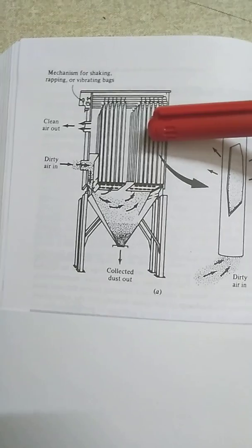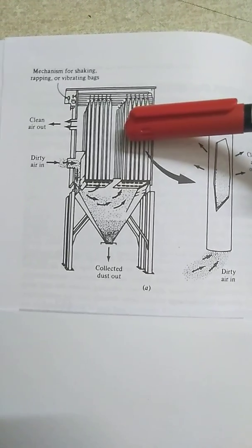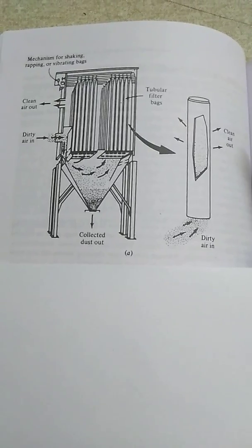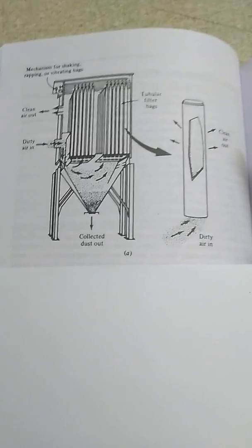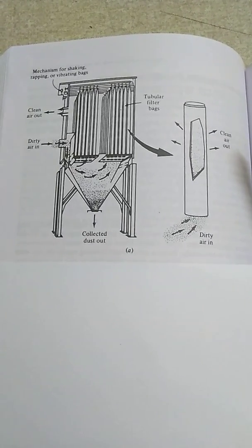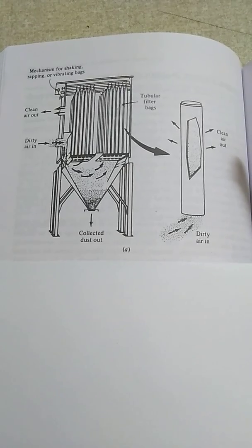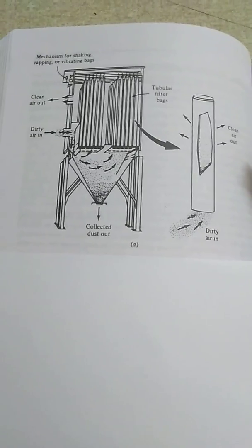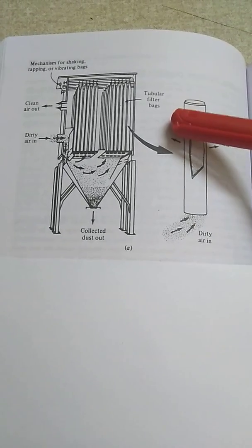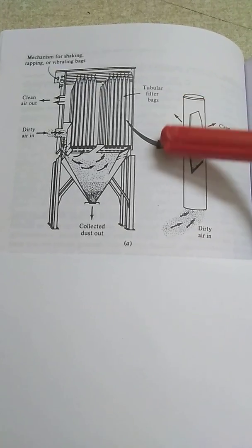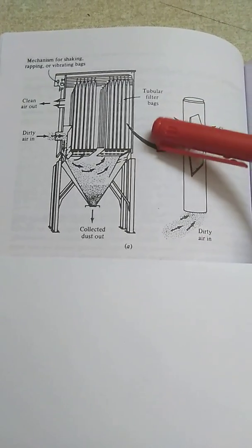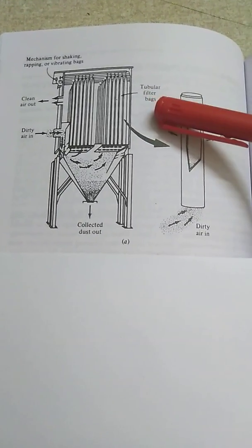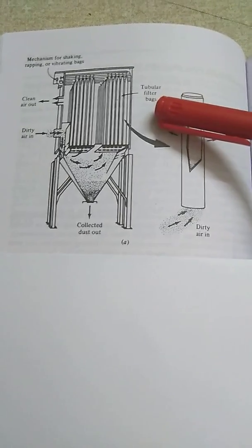Since we are using fabrics of a special quality, we need to restrict the gas that enters the fabric filter to a temperature of around 300 degrees Celsius. The next problem is, if very fine suspended particles enter this fabric filter, we cannot remove those suspended particles, and sometimes hygroscopic dust is going to create a problem. It is going to have some effect on these fabrics. Next is chemical attack. When gases like SO2 come in, they create a problem in these fabric filters.